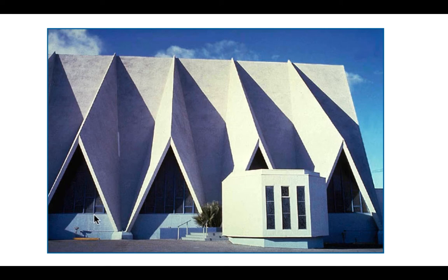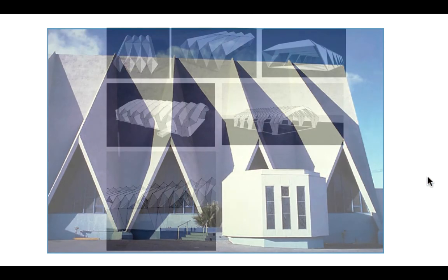And you can see deeper here at the edge, skinnier at the top. So in section, this is working really as a three-hinged arch, right? That has a place where it can rotate at the bottom, a place where it can rotate at the top, and the folded plates on the other side are kind of leaning against one another at the top, stabilizing one another at that top ridge.